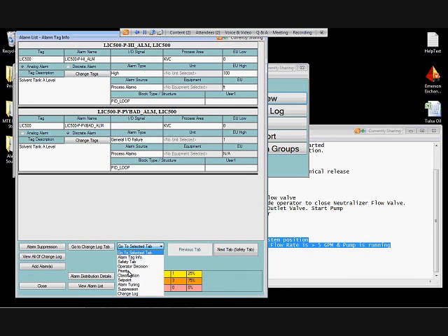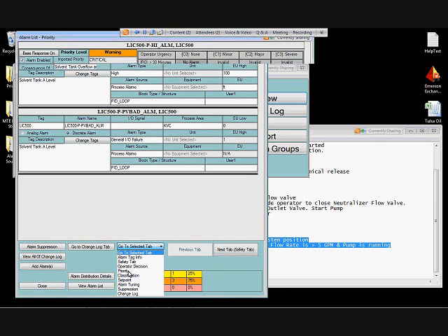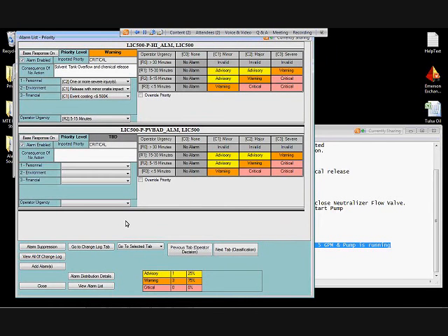And according to our philosophy, we've said that diagnostic alarms should be routed directly to the maintenance folks and not presented in alarm summaries with other alarms. So that means we're going to prioritize these differently. We're going to manually set their priority as dictated in the philosophy to the alert priority scheme that we saw.